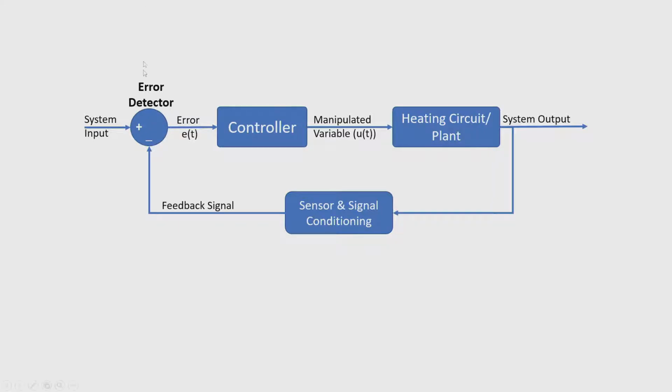So in LabVIEW I will be developing the error detector, and the system input will also be controlled by using LabVIEW user inputs, whereas the controller can also be realized inside the LabVIEW environment, whereas the plant as well as the sensor will be externally connected to the data acquisition system, where it acquires the data and displays it on the LabVIEW device.